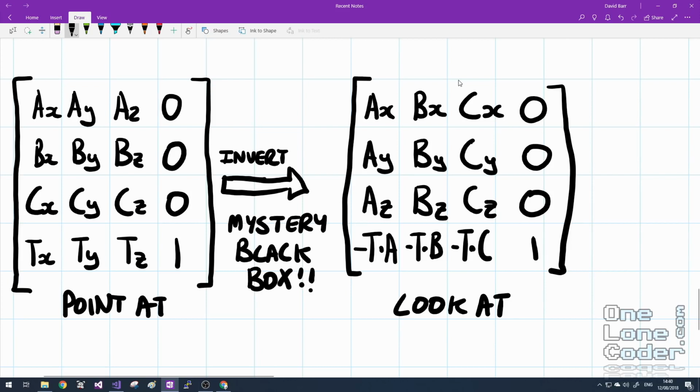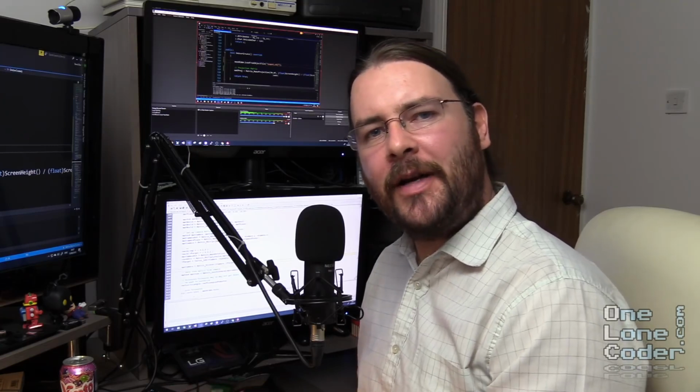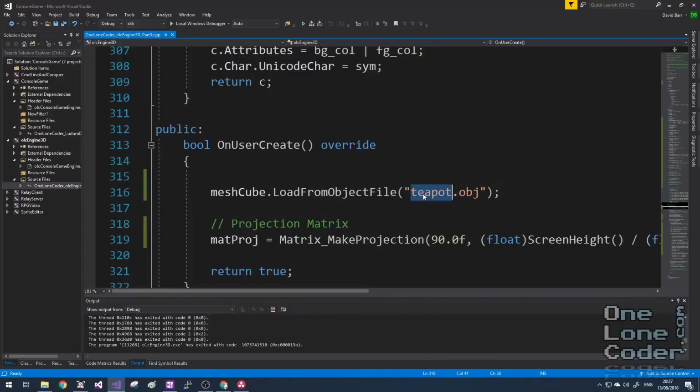And we can position that camera anywhere in world space, and we can make it look at almost anything in world space. So now I think it's time we add a simple first-person shooter-like camera to our engine, so we'll be able to walk forwards and backwards and rotate on the spot. We'll also add in up and down so we can get some elevation in our scenes to inspect them from different perspectives. I always find it useful when working with cameras to have a 3D object that represents the axis and the directions of those axes in space. Because when you start playing with cameras, things get weird quite quickly and can often become inverted.